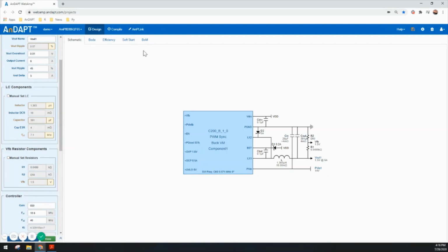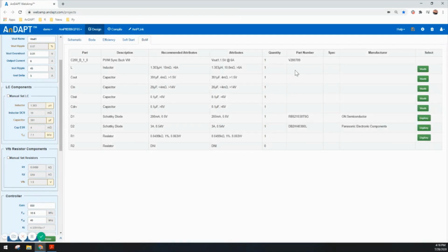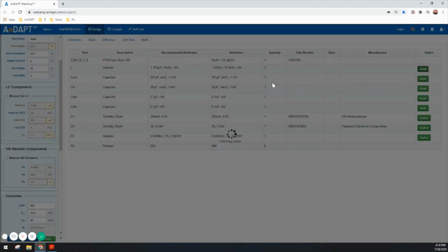For this application, we have incorporated an inbuilt BOM tool, which scrapes Würth's website for the available standard sizes. If I click Würth, it'll show me different inductor sizes in the vicinity of the selected number. Takes a few seconds.